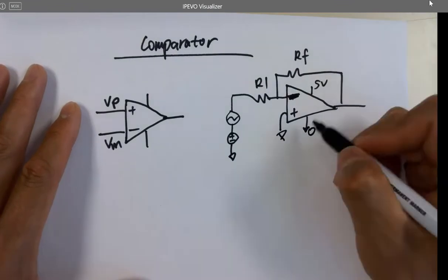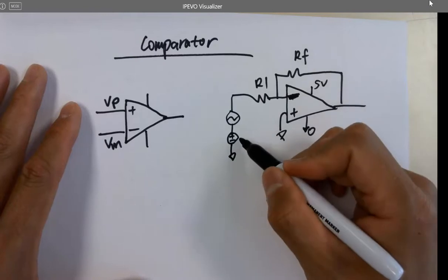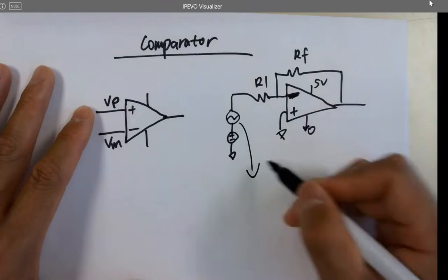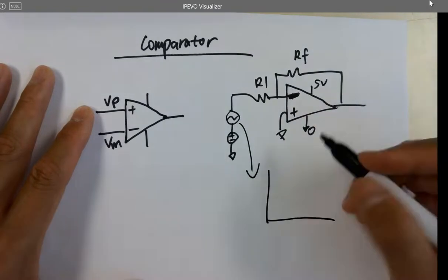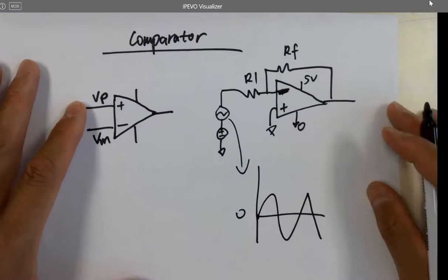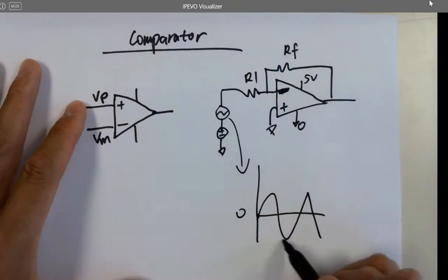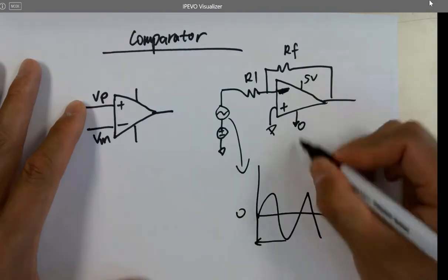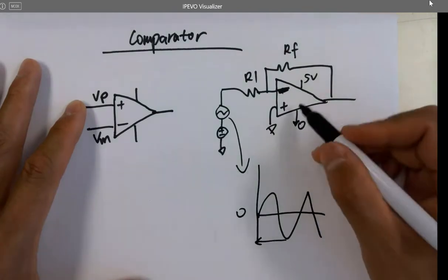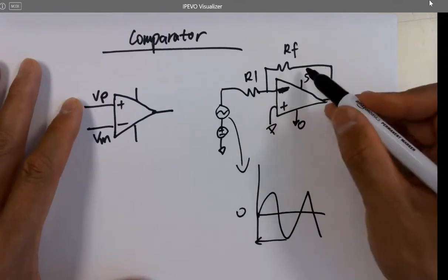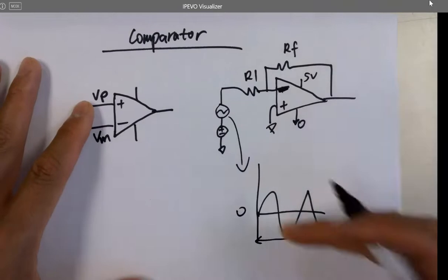Okay, so if you put a ground here and ground here, you need a DC offset to lift the signal. Otherwise, for example, this signal swing, there's no DC, right? Here's 0 volts, and swing like that, okay? And this already gets into the negative voltage domain. However, you don't have a negative voltage for the bottom rail. So whenever you're trying to amplify anything, the bottom will be cut off.